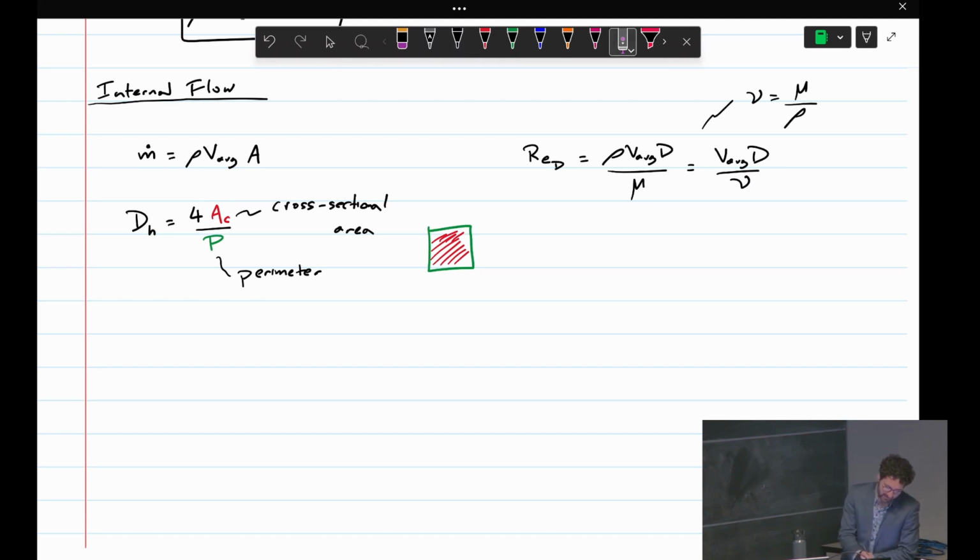So this Reynolds number, for many cases, in fact, the main purpose of the Reynolds number is to allow us to detect how much turbulence is in the flow, how much inertial motion dominates over viscous motion. So the top is kind of an inertial scale almost. It's a velocity times a length scale. And the bottom is just kind of the viscosity. So it's a viscous scale. So if there's a lot of inertial motion, we expect turbulence.